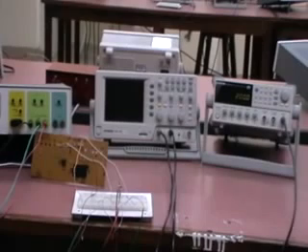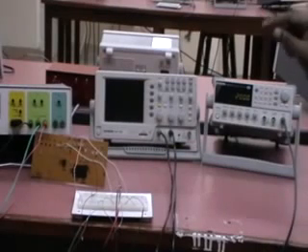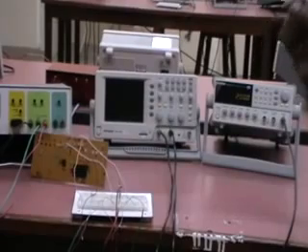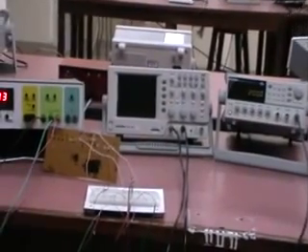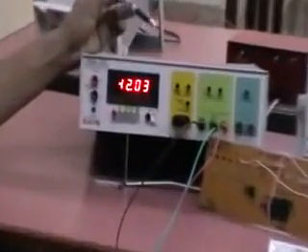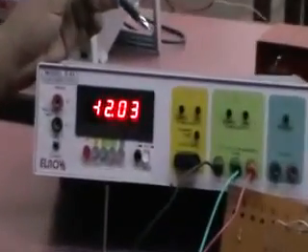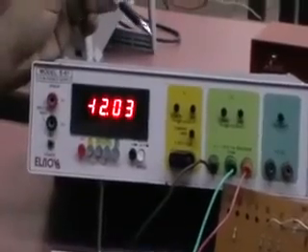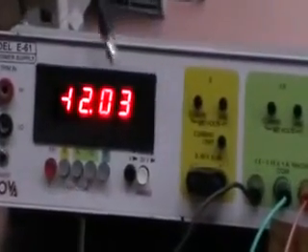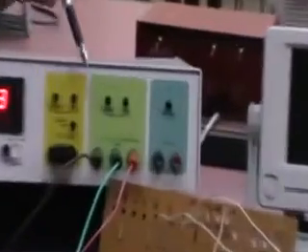Coming to the first part of the experiment, that is observing the IV characteristics of a diode. First, coming to the interconnections, we will give inputs of plus 12 volts and minus 12 volts from the DC power supply. So first switching on the DC power supply and keeping plus 12 volts and minus 12 volts, as you can see the interconnections there, by varying the coarse and fine knobs on the green part, you can keep plus 12 volts and minus 12 volts.